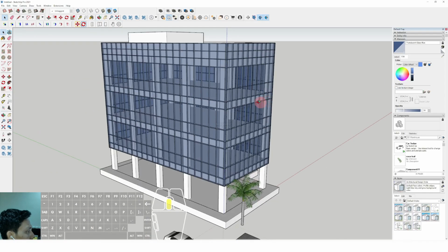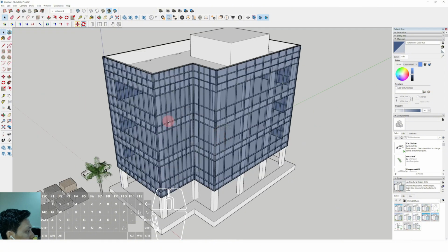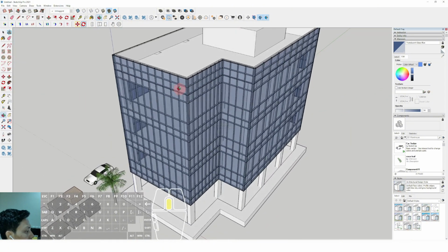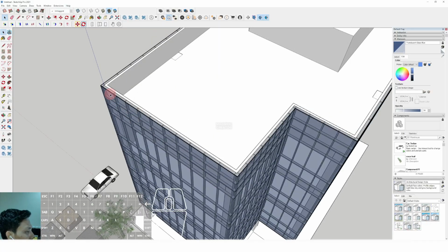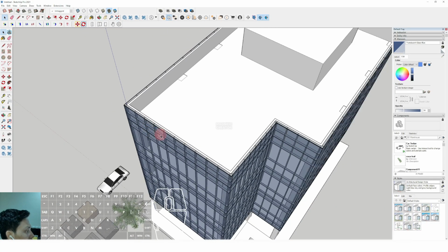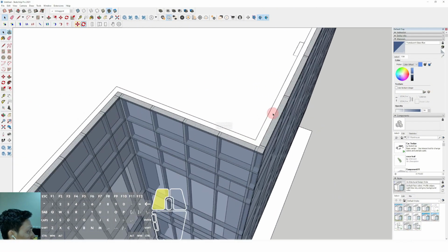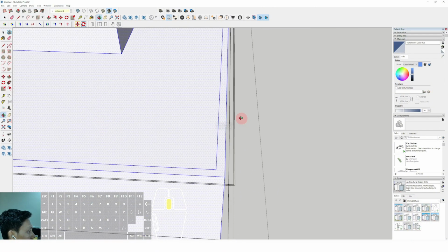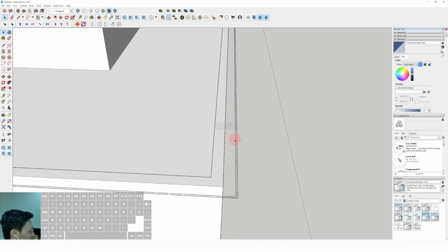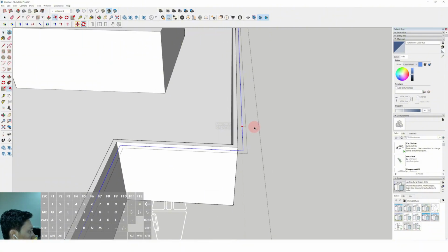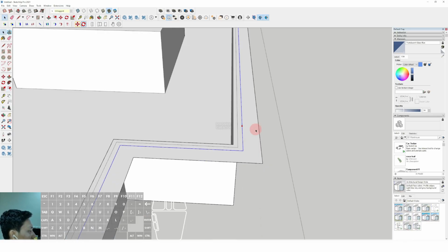So this is about the glazing color, and now we can make the wavy concept of the facade, and okay, we can use this wall again. Okay, then we can erase some unnecessary lines over there. You can triple click and offset it outside, okay, around 600 millimeter. Enter.